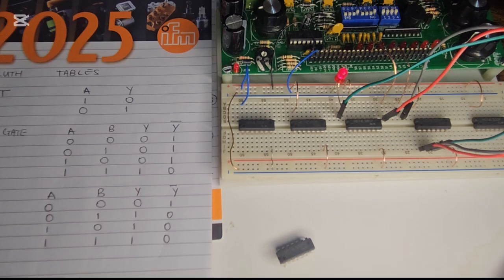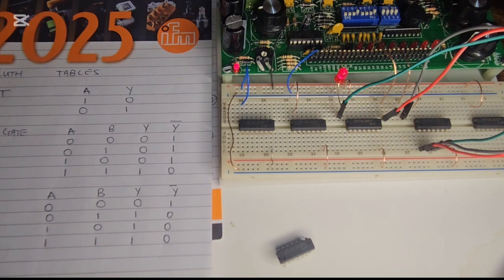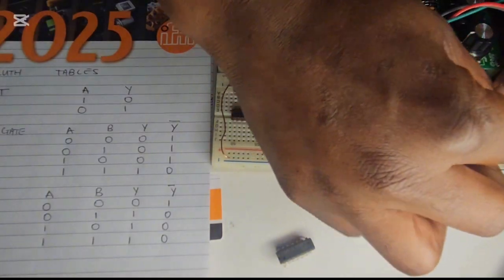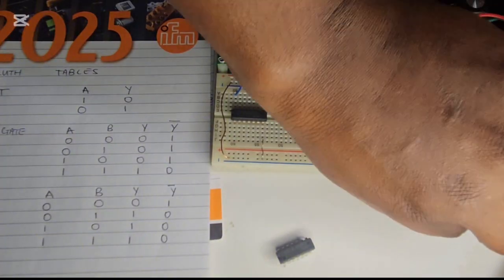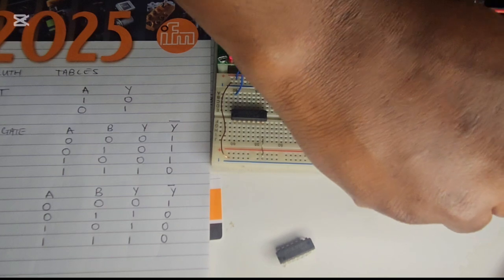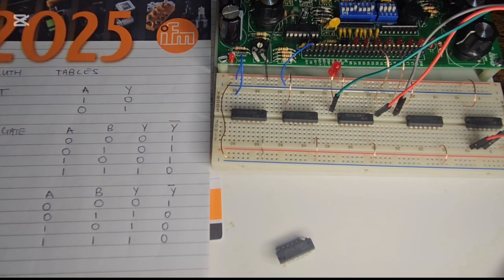Okay, let's test the last gate, which is the NAND gate. I'm expecting this one to be the opposite of the AND. Okay, we're just gonna move the wiring to that side. Pin number 3 is located for the output. Pin number 1 and 2 are your inputs. It's got many sets of inputs, but I decided to use just the first gate on all these circuits for simplicity. Okay, now, so this is my NAND gate.